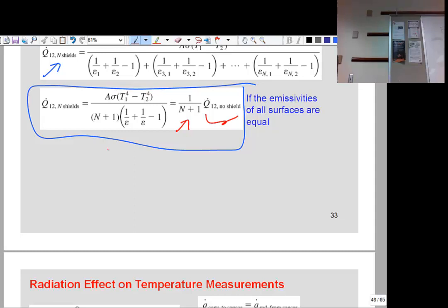But look at that. He asked for watt per meter square. So basically he's saying just give me Q by area, Q dot 1,2 by the area. That is all he's asking about. So we know the sigma, 5.67 times 10 to the minus 8. T1 to the power 4, that's 600 Kelvin. Make sure it's in Kelvin.